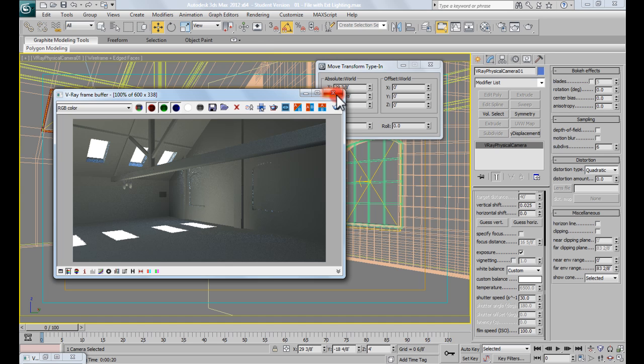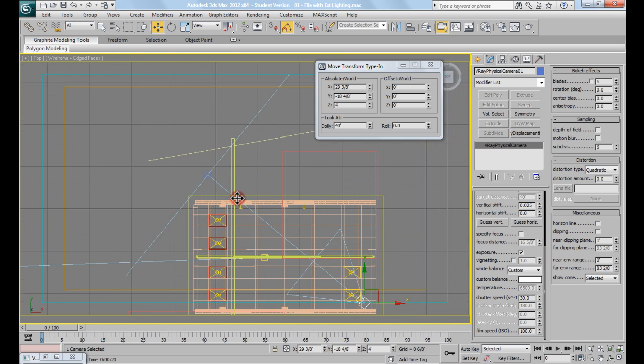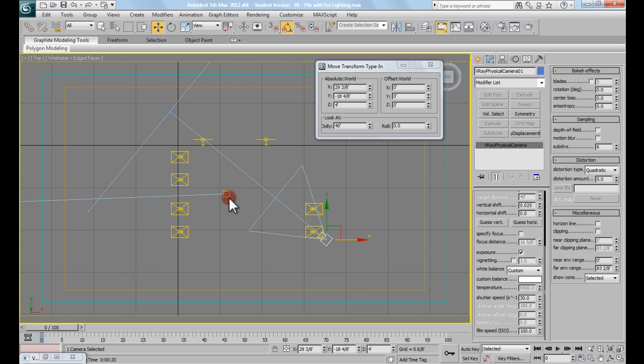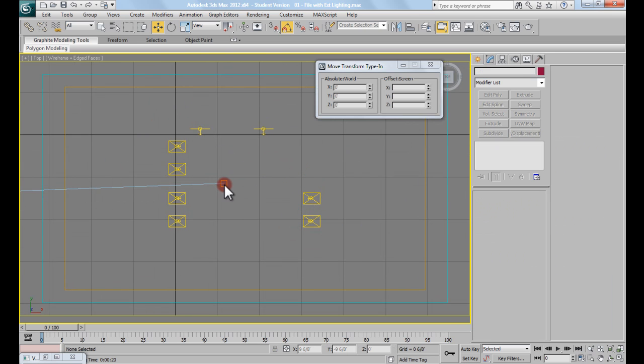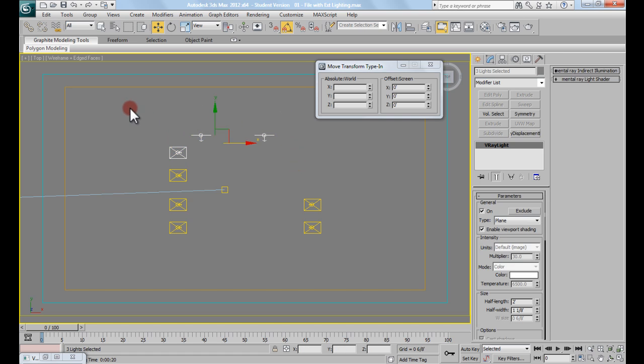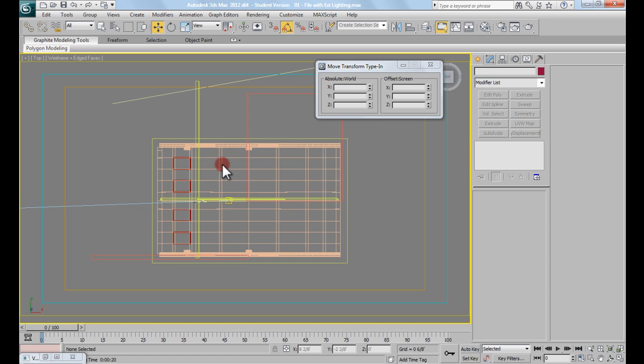Now the other thing, I mentioned there's two different ways you can do this. So if I hit T for my top and Z for zoom, I'm just going to hit Shift G and hide my geometry, and Shift C and hide my camera. I'm going to turn off my grid, just personal choice there. So I'm going to delete out my skylights. And then I'm going to hit Shift G and show my geometry again.